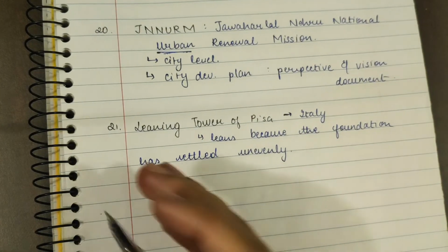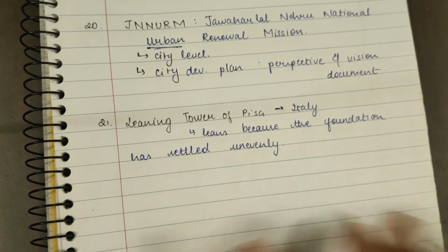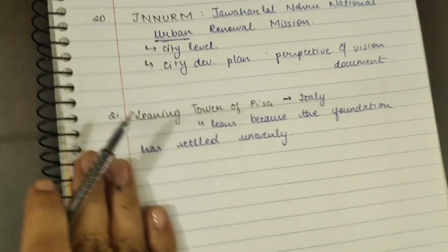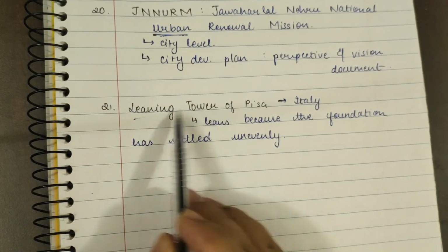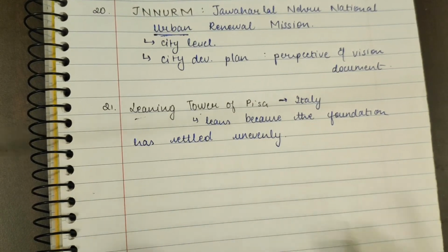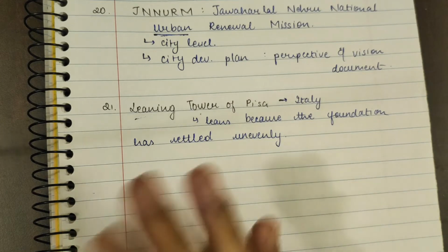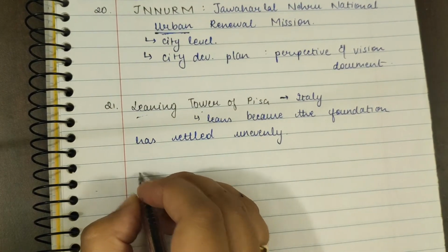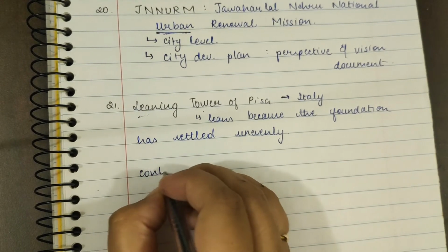Because it was made a very long time ago, obviously they did not have the different instruments to check the different types of soil present at different depths of the earth. It is also situated near a water body, so that's why the foundation soil shifted, and the foundation was settling down unevenly. But basically this has been controlled or